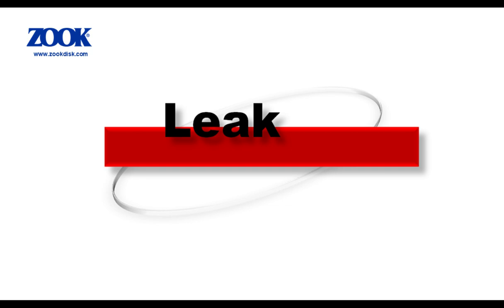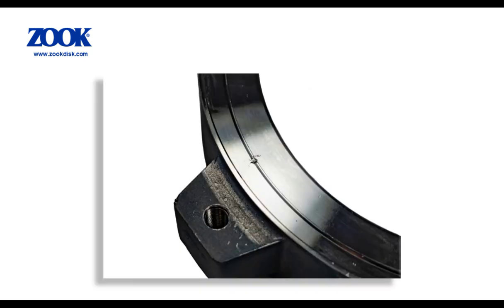There are various methods used to seal the rupture disc within the assembly. This varies from manufacturer but can include O-rings, pinch points, welds and metal bite rings. Care should always be taken when handling holder sealing surfaces and they should be inspected every time a disc is changed. Any damage to a sealing surface can cause leaks. In this picture you can see that the raised sealing bite section of the holder has been damaged, which could create a leak path in the assembly.